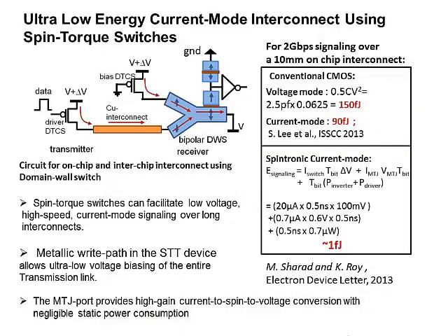Now let us look at how we can use the same device for very low power data buses. Here we show a current mode interconnect based on the proposed spin torque sensor. One of the inputs is connected to a reference current, which is again flowing through a very small voltage, and the other input is receiving the current mode data across the copper interconnect. Here we have a long data bus, which can be of the order of 10 millimeter long, and it is receiving a current mode data input from a driver across a very small terminal voltage.